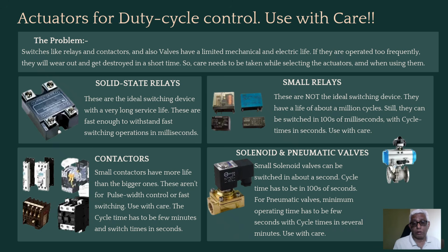All right. On-off valves, smaller on-off valves, small solenoid valves, pilot operated diaphragm valves. These have to be operated within a minimum. They require a minimum interval of about 1 second. So you can have a cycle time of 500 seconds, 5 second minimum operating time. That is allowed. Okay. The smaller the valve, less can be the cycle time. Just see the data sheet.